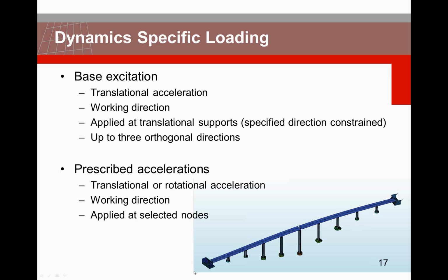But for long constructions like bridges, it is not always wanted that on all supports, say on all these piers here, the acceleration, the earthquake starts at the same time, because this earthquake has a traveling time. In that way, we can use prescribed accelerations. These can be translational or rotational. Also, these have a working direction, and you can then apply them to a set of nodes.